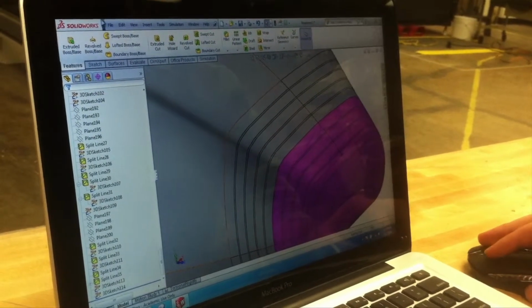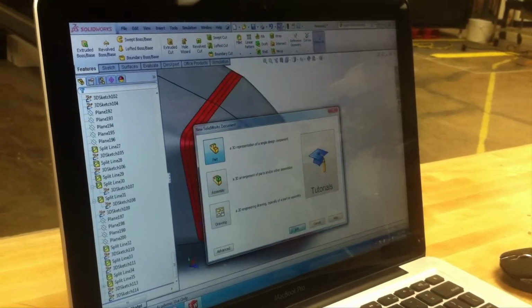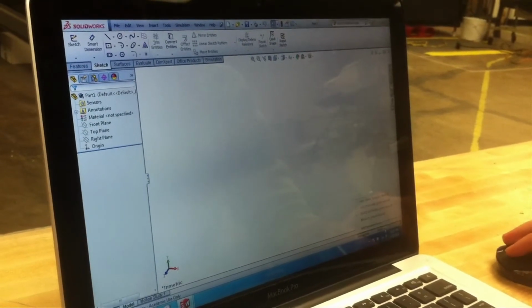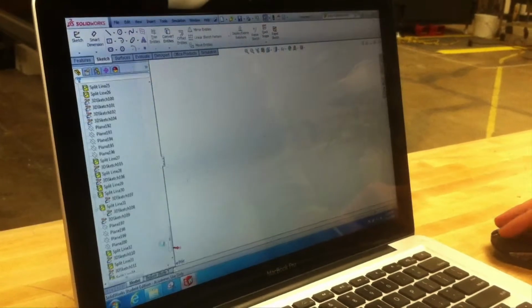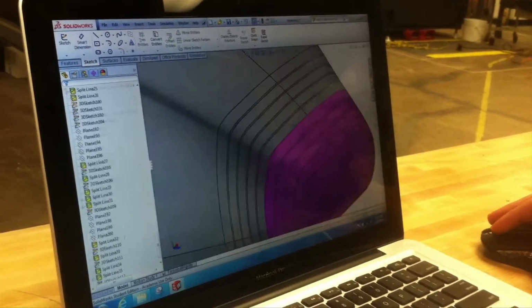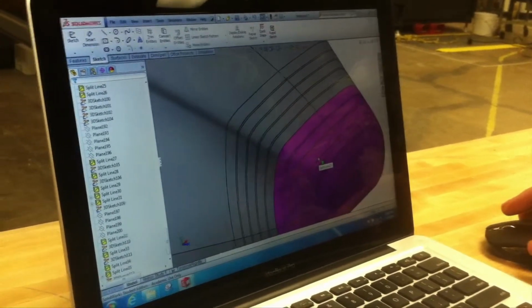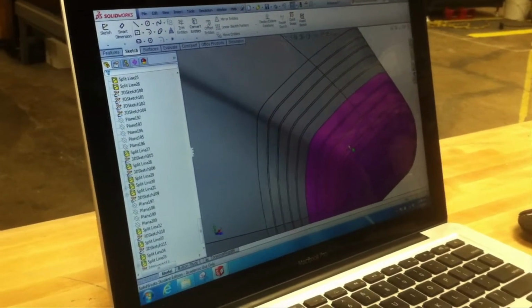So first thing we're going to do, going to open up a new part file. One thing, very important. Make sure that it is in inches. Okay? Here, inches. Make sure it's in inches, as well as make sure this is also in inches. It just works out better for AutoCAD, the foam block that we have. Well, that and it reads in inches on the routing computer program.